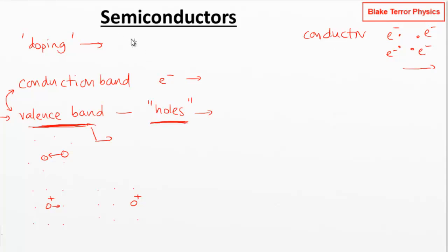So coming back now to doping, there's two ways you can dope a semiconductor. You can dope it with holes. That's often done, you might dope it with boron. That is adding holes. That gives us more holes, which means we're getting more positive charge, really, because these holes are absence of negative charge, they're positive. So you get what's called a P type, P for positive, semiconductor, because we've doped it with holes. Or you might dope it with electrons.